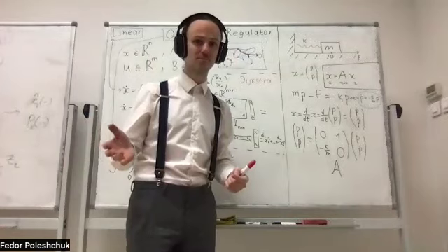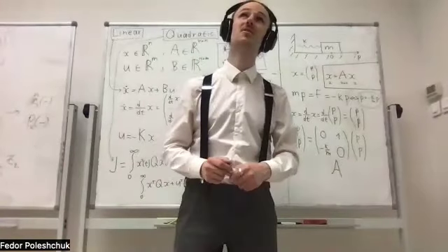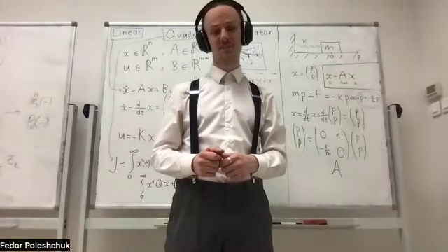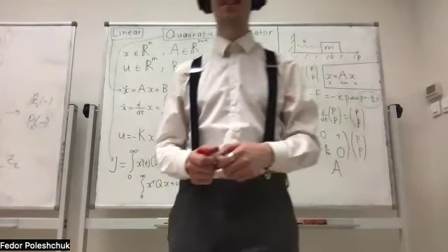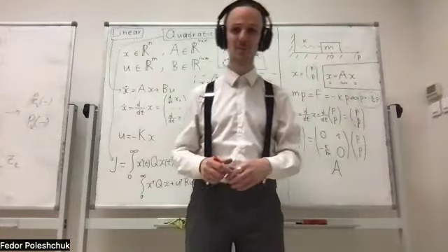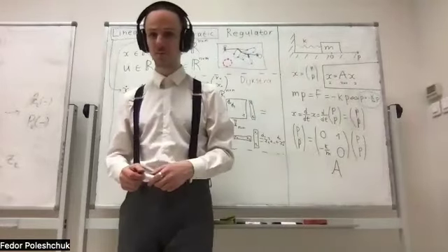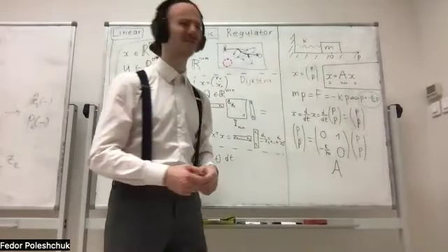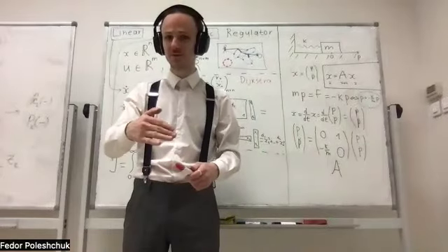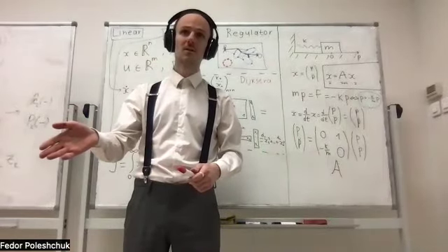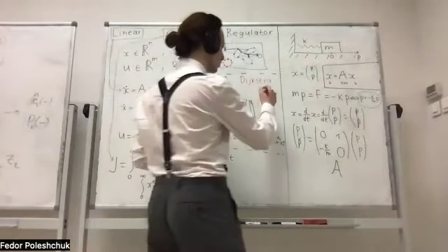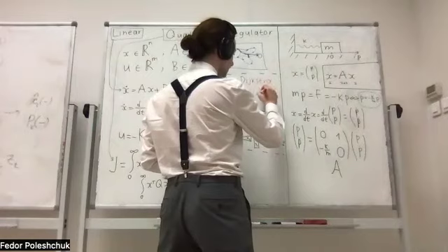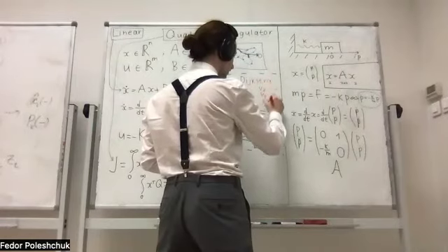It has basically 3 types of steps: forward, which is the same as backward but with a different sign of the speed, side step, and rotation. I mean, it can go along curves. Generally speaking, the command could be formulated as Vx, Vy, and omega.